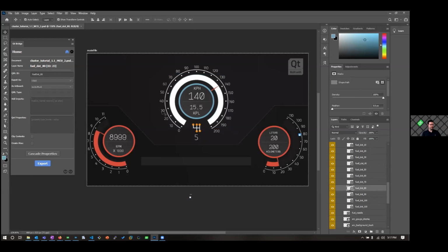And that's an optimization that's worth noting, especially when you're dealing with a microcontroller where you have limited RAM and flash space to work with. You don't want to have to bake in 50 different images for the same look and feel. And so by doing this, I'm able to reuse that and avoid that extra overhead.